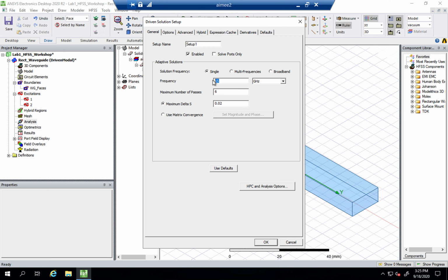So that means here, if I select 15, if I want to look at the results at 20, I should be careful. I shouldn't trust them that well, because 15 is less than 20. But if I'm interested between, let's say, 1 and 14 or 1 and 15, then the meshing should be good.